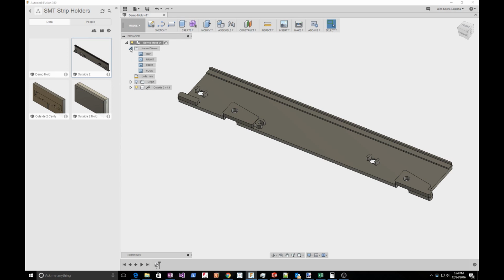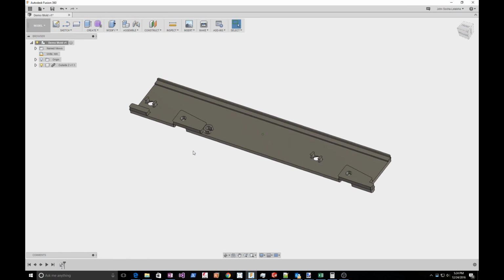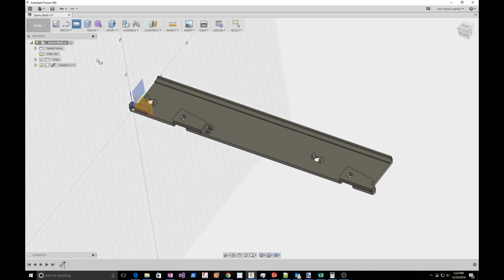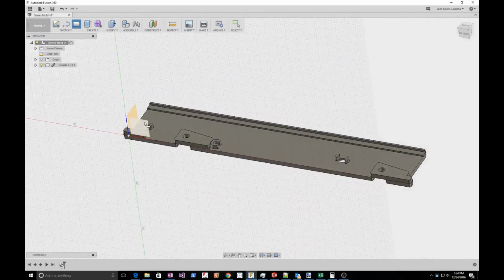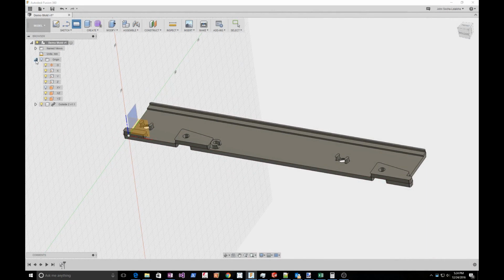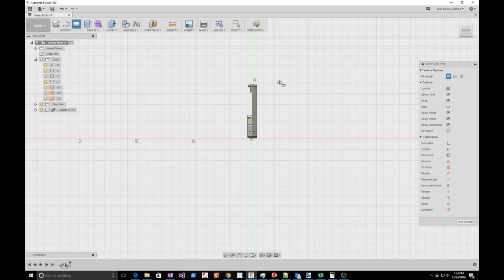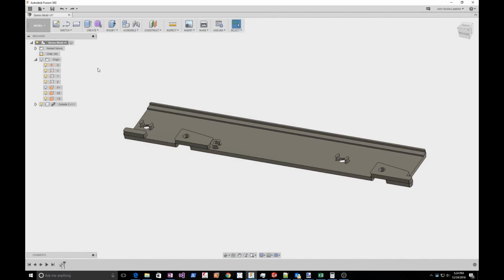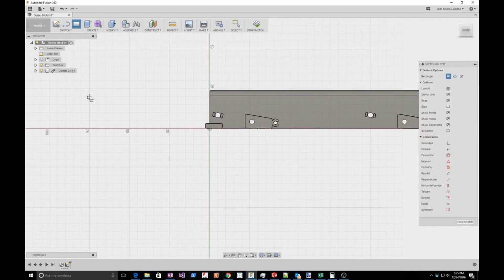All right, the first thing I want to do is create the mold half. And I'm using aluminum for this because it's cheap and light. What I want to do is create a rectangle. So I pressed R for rectangle, and I'm going to put it onto, I must have hidden one of those. Yes, I did. Okay, so I want to put it, oops, let's undo that. Not sure what happened. Turn that back on. Press rectangle, click on there. There, that's what I want.